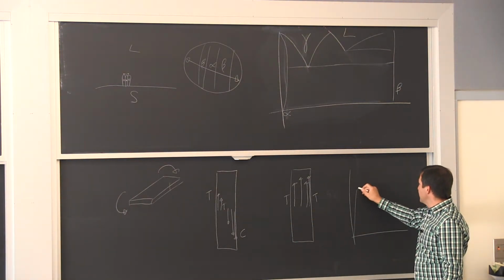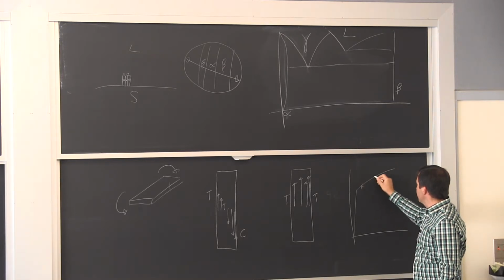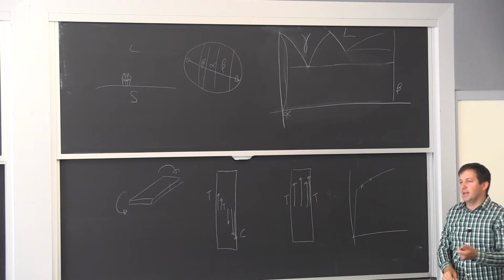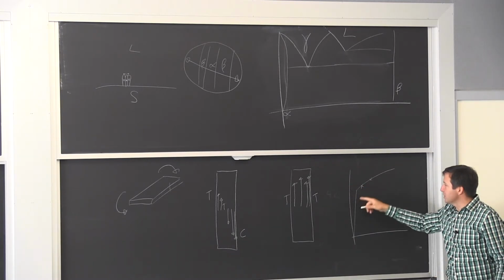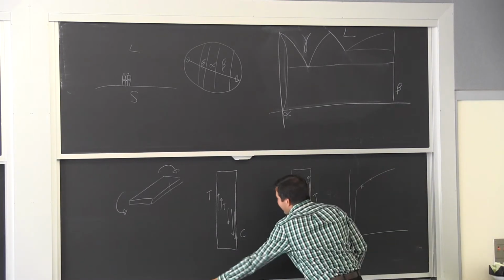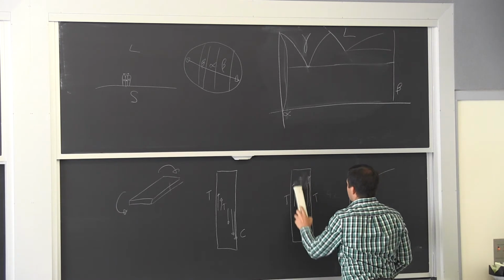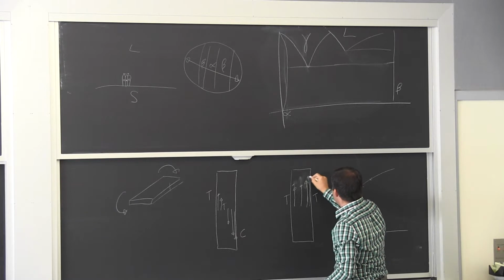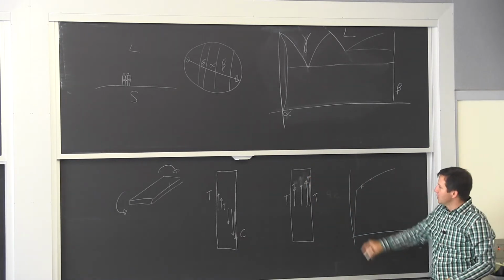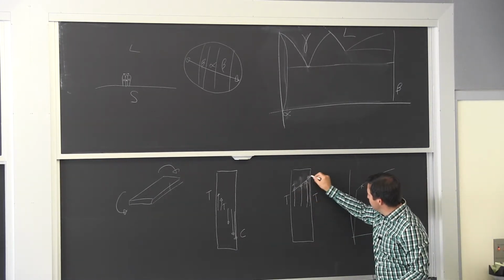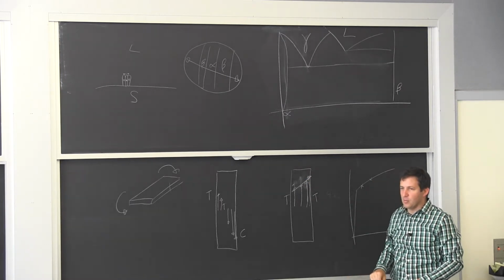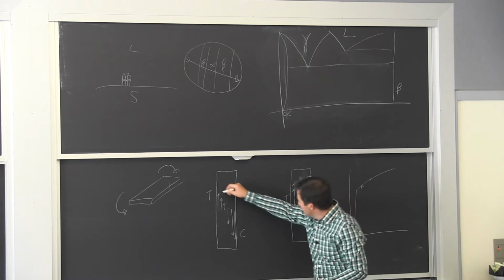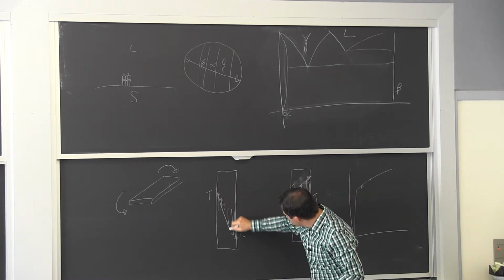But when you get in tension between here and here, yes, you do get the differential strain that allows you to bend. But when you're looking at the stress level, to be fair, and make sure you agree with me, I'll just put a little gradient here because of the strain hardening for creating the curvature. So in the end, this is essentially your bending moment that's going to be with you when you unload, and over here you've got it going much bigger.